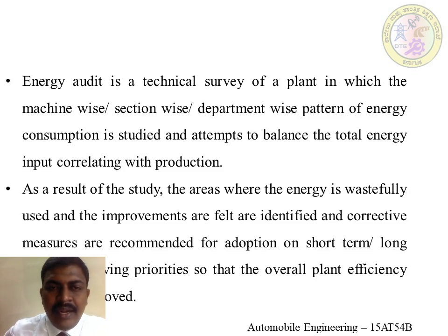So the energy audit is nothing but a detailed study of a plant in which the machine wise, section wise, department wise energy consumption pattern is studied, and an attempt is made to balance the total energy input correlating with the production.